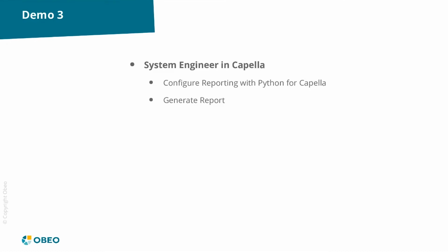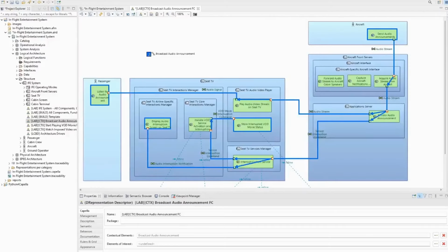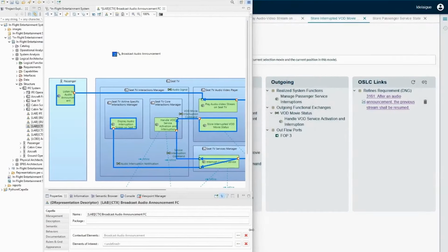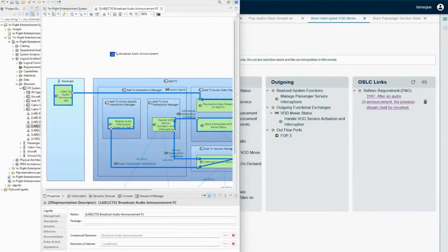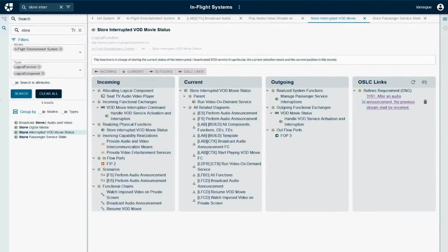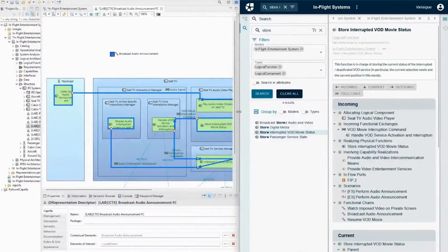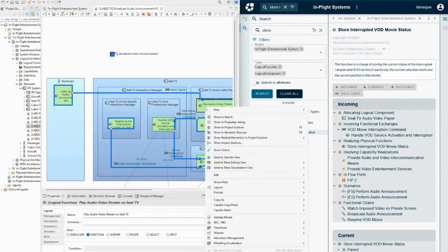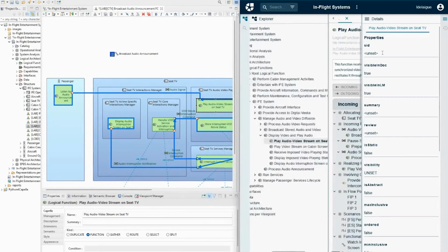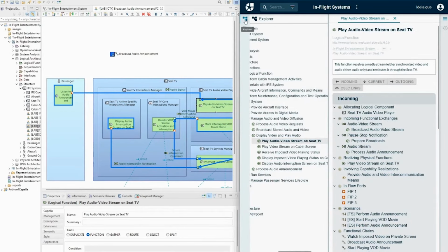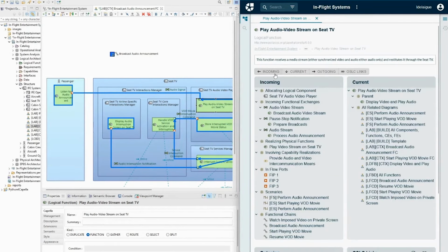I forgot to show it before, so I will do it before I forget. Sorry about that. Just a small feature regarding the first topic. When you're in Capella, it is also possible to navigate to the online counterpart of your Capella model elements, which is nice to do. You right-click on the function and you can see it online. So you have this show online entry point, and it takes you to the web page on Publication4Capella.